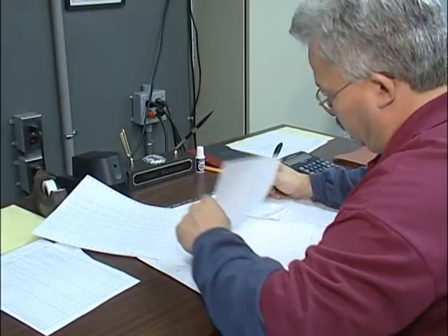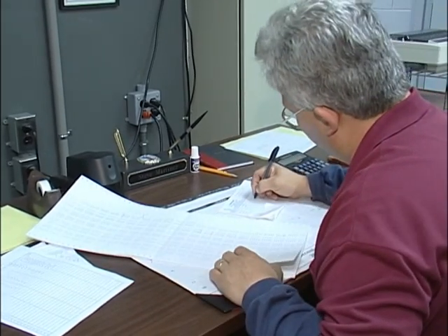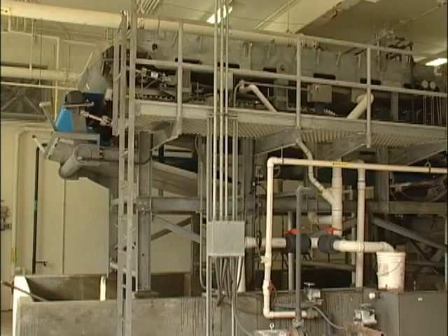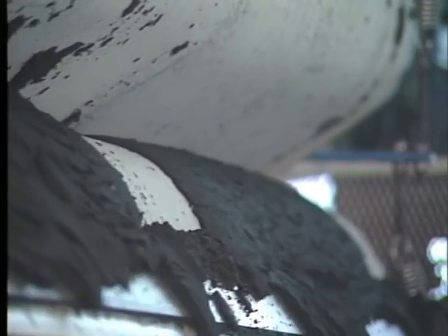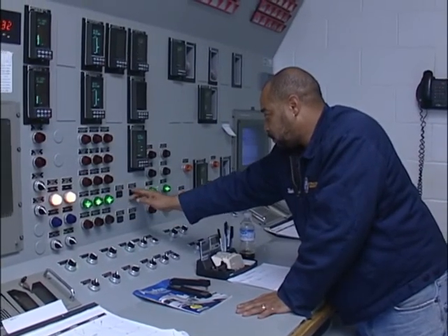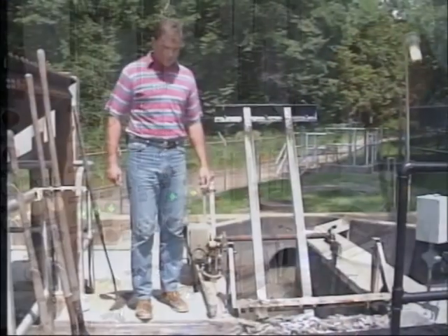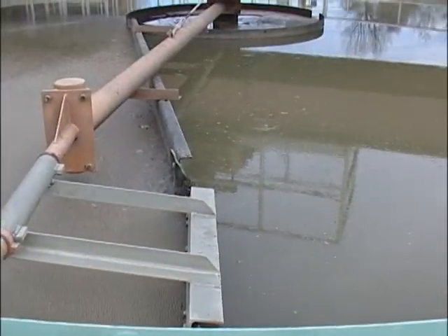It is important for the facility operator to document the amount of ammonia generated from all sources. For systems that have anaerobic digestion or that produce filtrate from belt presses, thickeners, or other devices, it should be noted that these process flows can produce a large quantity of ammonia. This is especially true during periods of malfunction. This makes monitoring and adjustment of these processes a critical factor in maintaining compliance. Always remember that solids handling processes and processes upstream of biological treatment processes can dramatically impact loadings and efficiency.